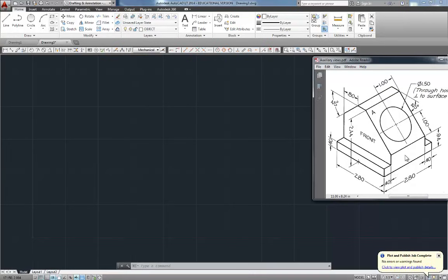The right side view, however, would not properly show this circle for us because that circle is on a slanted surface. And if I were trying to produce a dimension drawing, which you'll do a little later on this semester, I can't place a 1-inch dimension on a slanted surface in a view because that view is foreshortened, as we would call it. It looks much shorter than it really is.